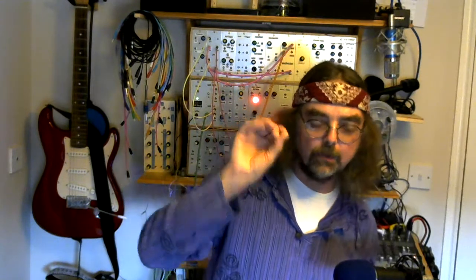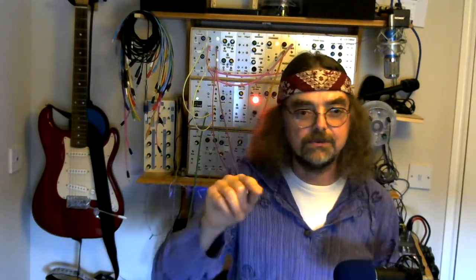So what I can now do is generate sub-octaves of the original oscillator frequency. In actual fact, on my module I generate 3 of these and then put them together to a single output, so I can simultaneously have my original sawtooth output and then use the pulse wave output as a clock signal to generate square wave sub-octaves of that original oscillator output.